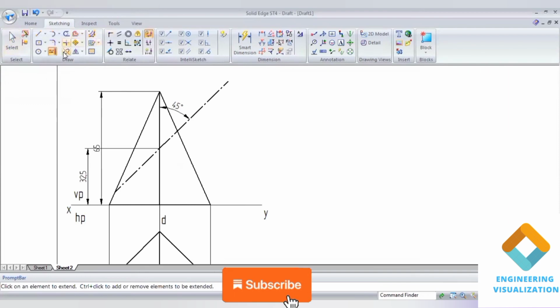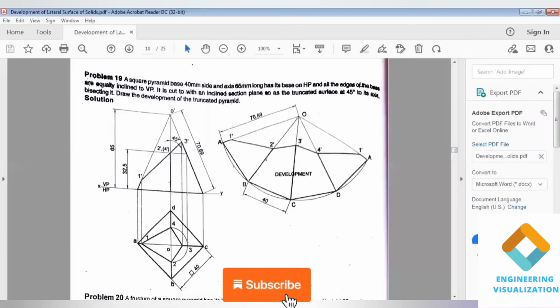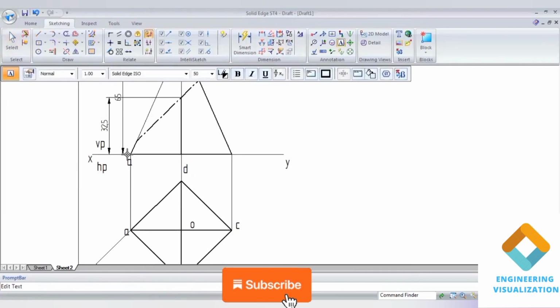Now I am going to make the upper portion lighter in order to show that the lower portion is the cut portion, the truncated surface. Now I'm mentioning the cut points here. So you can mention the front view notations: E dash, B dash, C dash, and D dash is not visible from the front view.